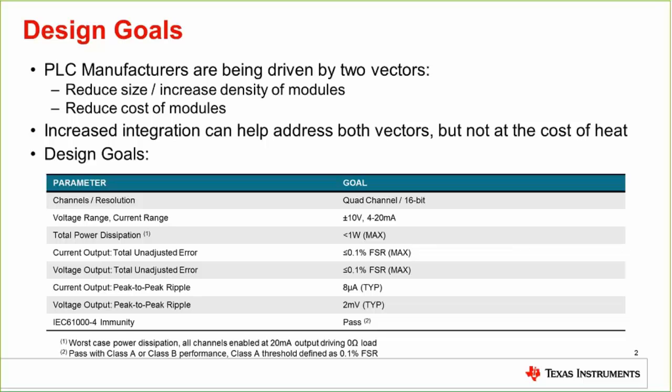And at the same time, we have to be mindful that manufacturers or designers in this particular space have to go against pretty stringent immunity standards represented by the IEC 61000-4 immunity goals, which is ESD, EFT, or electrically fast transient, conducted immunity, radiated immunity, and surge.